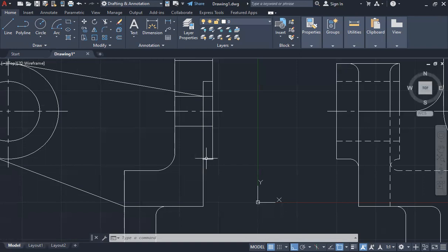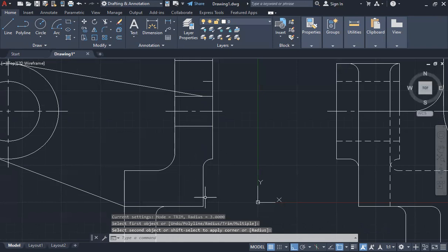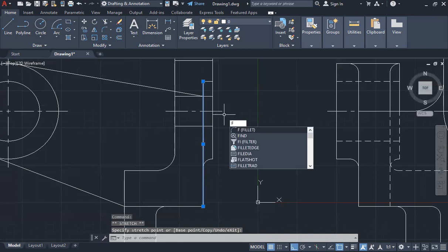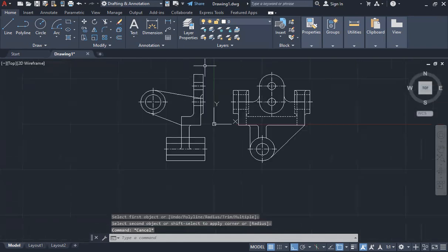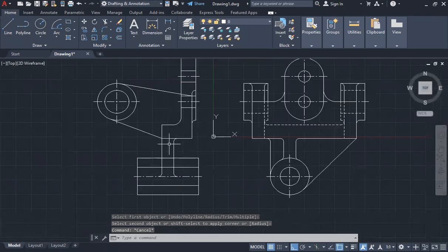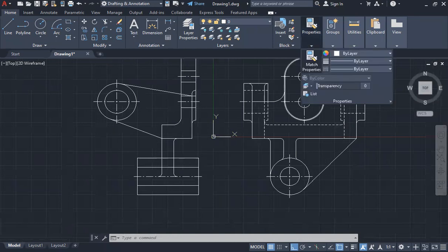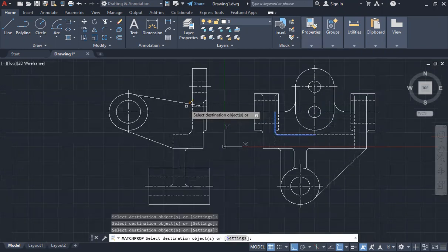Okay, we also have 3 mm fillets here. So fillet, extend this line. Again, fillet, 1, 2. I'll change my line types to hidden. So I'll go match properties, select one hidden line this side, and select my hidden lines on this drawing. Okay. All my hidden lines.